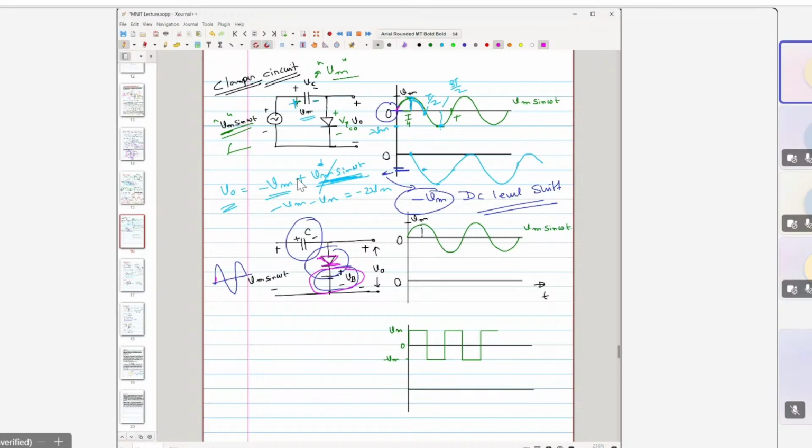So the input voltage has to cross this VB, only then this diode would turn on, right? And then this capacitor will start building the potential across it. Now say this is turned on. If the maximum amplitude is Vm here, what will be the maximum potential that this C can hold? Now it is not anymore Vm, but it is Vm minus Vb.